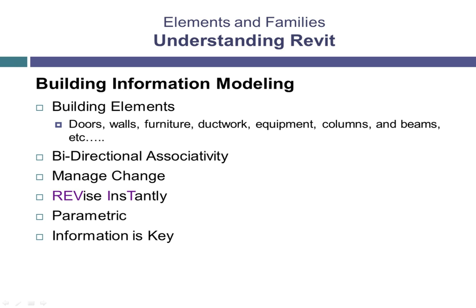Architecture and engineering projects don't usually have Hollywood-style budgets, so you need to find the right balance of efficiency and usefulness for each project model. In many cases, items only need to be loosely represented, and can even be depicted in 2D when they just need to be specified by the designer and quantified in the model. Keep this in mind when planning how to use Revit on your projects.